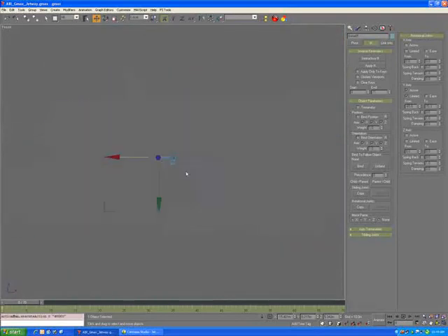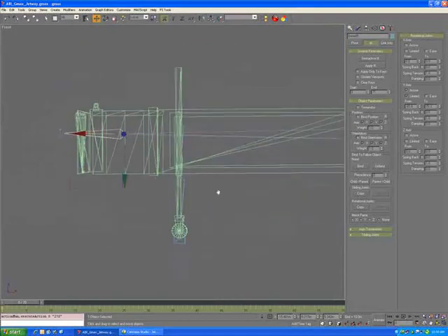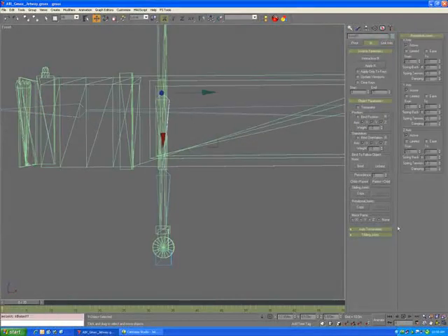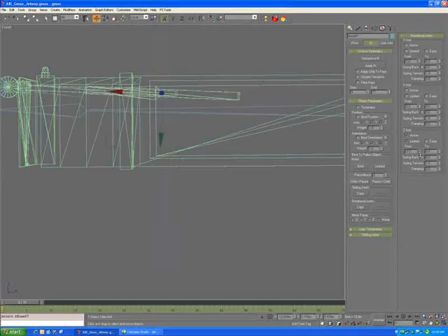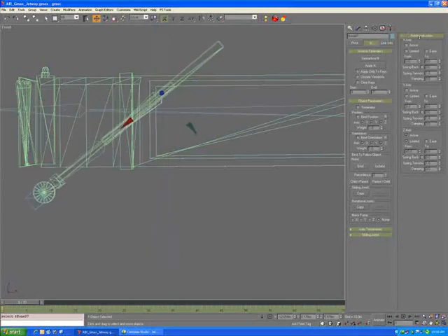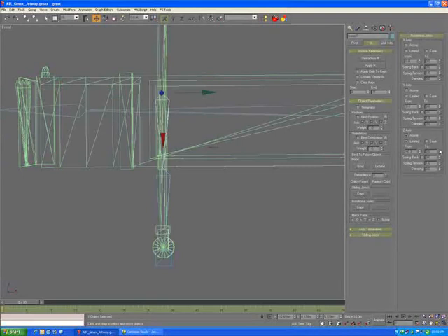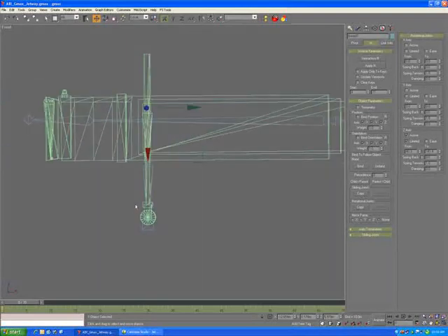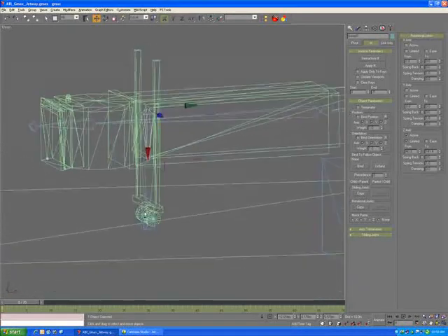So the next step is to do the legs of the jetway. And once again, we're going to select this bone here, no sliding joint in this case. And in this case, it looks like the z-axis is the one that's rotating. So we'll turn off the y, turn off the x, and limit the z. And so it will go from about there to about right there. And it may never solve to that point, but it's good to just allow it to get that far.